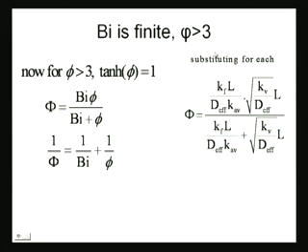So next, what we are always trying to do is find out what my observed Thiele modulus is, or in other words what my observed reaction rate is, based on other quantities, because I am a little lazy and I don't want to be measuring the actual reaction rates. So what I do is very straightforward. Simply in this formula I put in my effective Biot number and the intrinsic Thiele modulus expressions in terms of the effective diffusion coefficient, the mass transfer coefficient Kf, L the length, K average, which is the partition coefficient, and everything, and this is the formula that I get, which I can use.